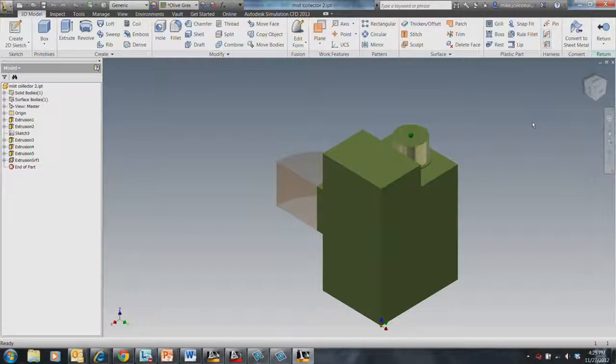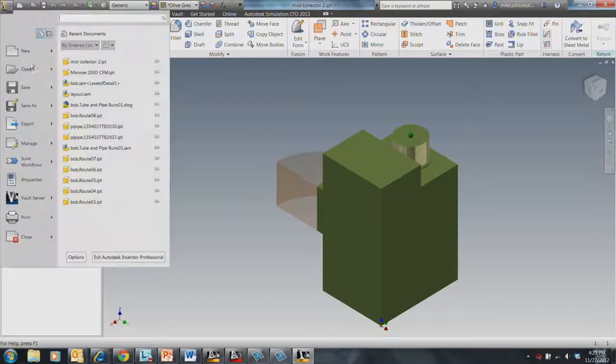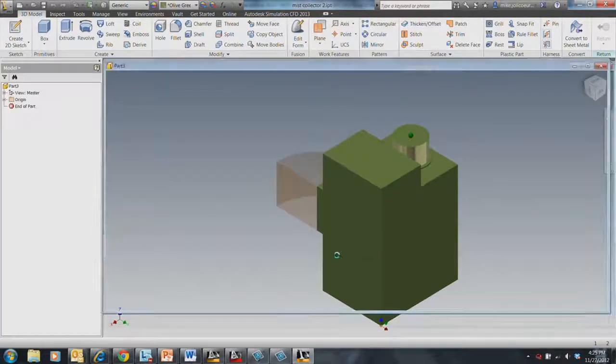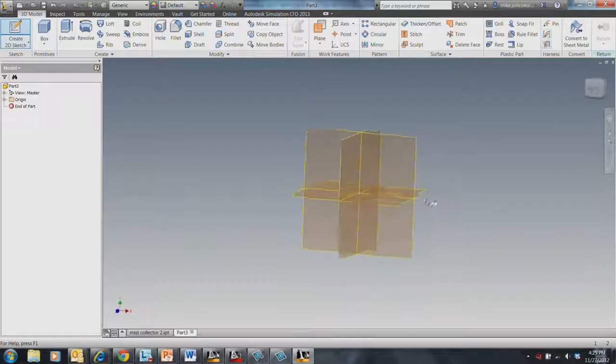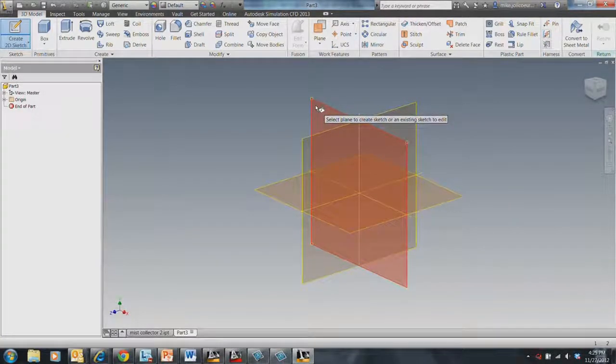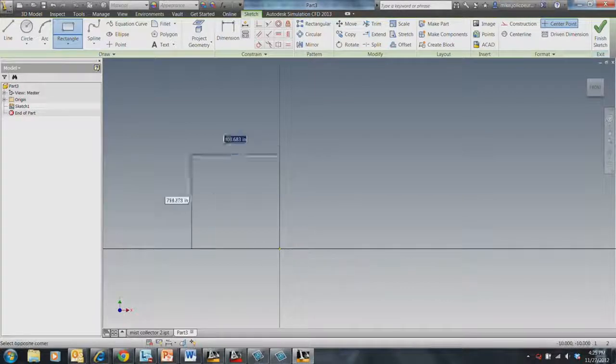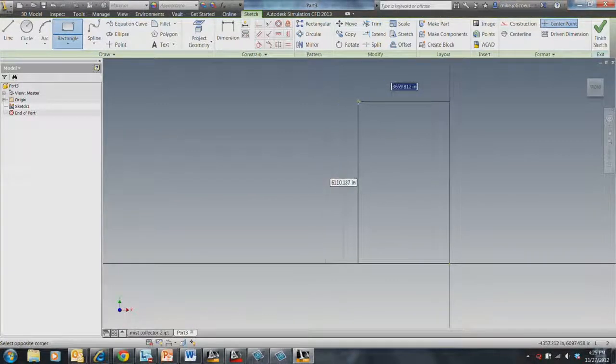We do a lot of pumps and tanks, and to make those 3D, a lot of times it's better to draw half of it, take a P-line, and revolve it in regular AutoCAD. Since we have some time, I'll go ahead and create one like that. So if we go here, it's exactly right. What you end up doing is just creating a rectangular section. In this case, maybe we'll make it 36 inches across this way, and 72 inches this way.